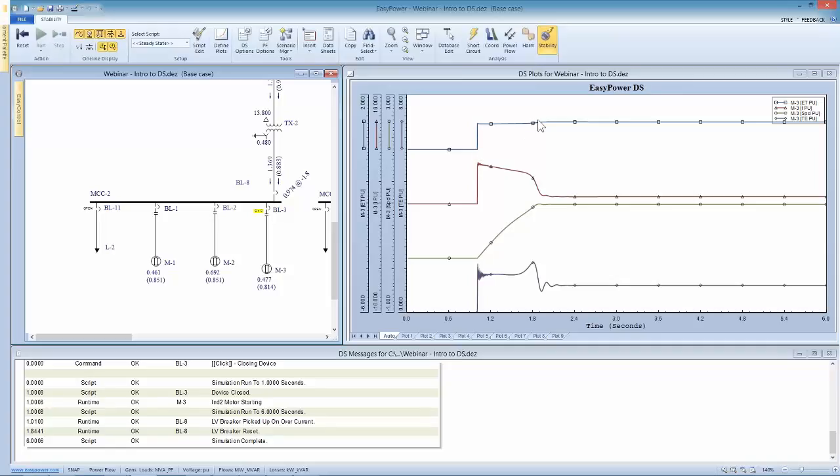We see there was a voltage sag, and then as it comes up to speed, the motor terminal voltage goes up to normal operations. So we have the terminal voltage and the per unit current, and it's high current as the motor comes up to speed and then drops down to quiescence. The motor speed is being shown, and then here's our electrical torque.